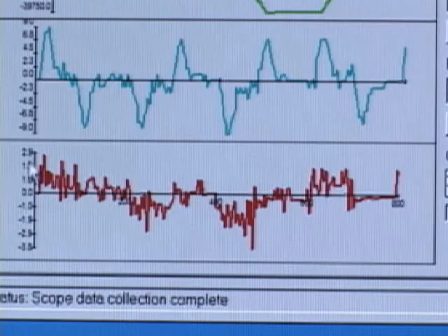There could be situations where the motor is working hard and the amplifier gives all it can, and the command goes up to 10 volts and it saturates the amplifier for a few milliseconds. And clearly, if you saturate the amplifier, you're out of control. And the system may be out of control for a few milliseconds, and there is no way to find it out unless you looked at the voltage throughout the whole operation and made sure that it always stays within the linear zone of plus minus 10 volts, preferably within plus minus 8 volts, so you have some voltage to spare.